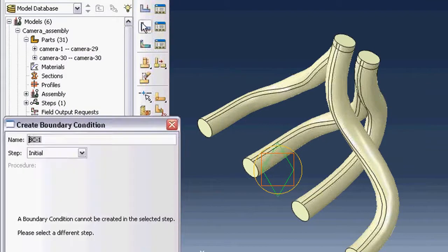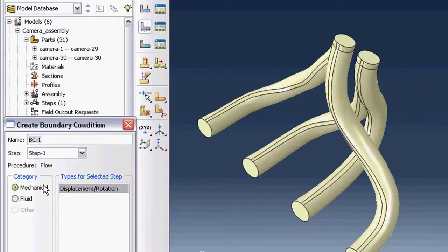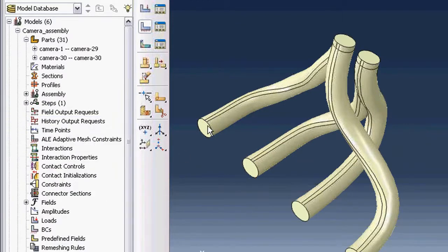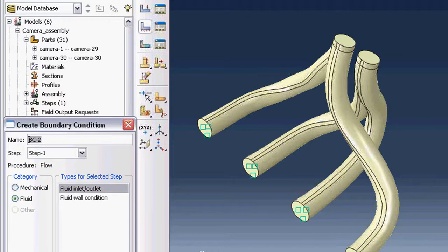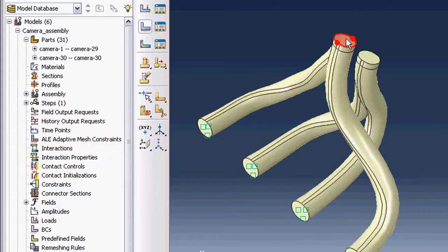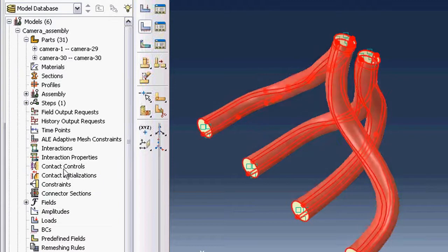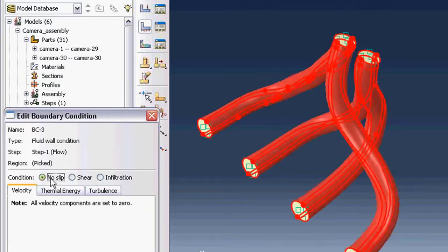Some of these surface repair works and mesh repair works and supplementary 3D modeling works that you've seen done here, they could also be done in the original computer-aided design package, of course, whether it's CATIA or SolidWorks or something else altogether. But it's worth considering that often the experts running analysis may not even own a seat of that CAD program, or may not even be familiar enough with the program to know how to use it. So it's helpful to have these tools that they can use to repair the analysis models and meshes right there in the analysis program.